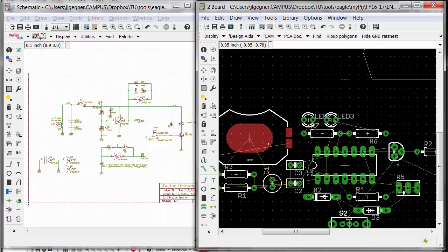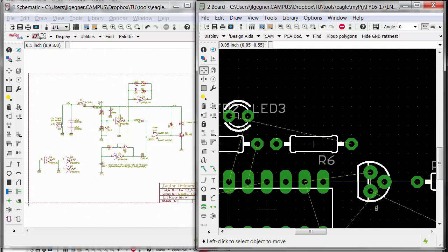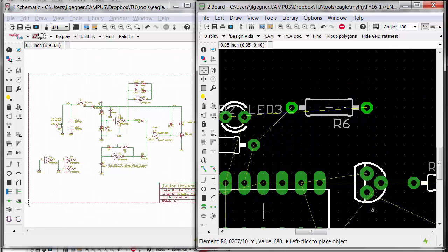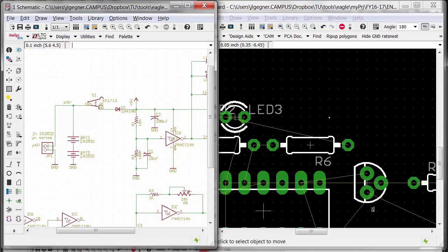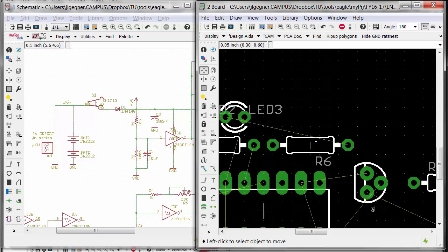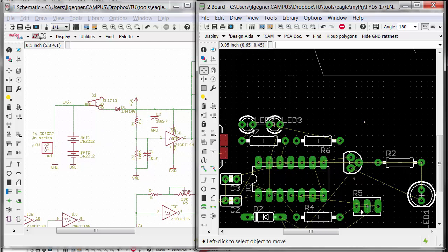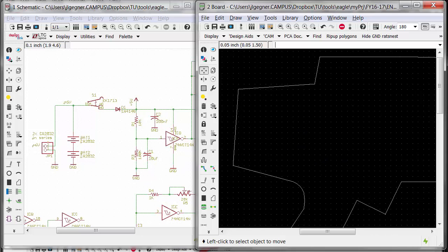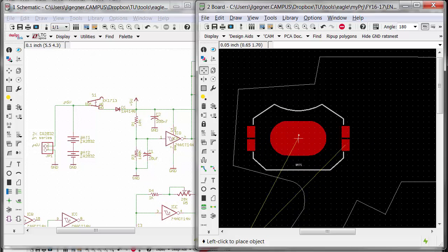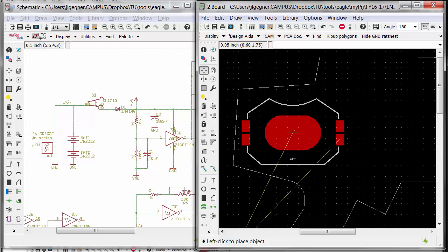All right, now you can move parts one at a time, like go down here and say, okay, I'll move this guy here. Let's see where he goes. But what I prefer to do is reference the schematic and actually type in the reference designator that I'm trying to move rather than going and hunting for it. So I kind of work through the schematic and place things as I see fit. So for instance, I start over here by the battery, and I have a BAT1 and BAT2. These are those surface mount battery holders, and I want to place them in this area. So I'm going to click the move command, or Control S, and then I can just type in BAT1, enter, and right there it puts the BAT1 in motion, and I can place it.